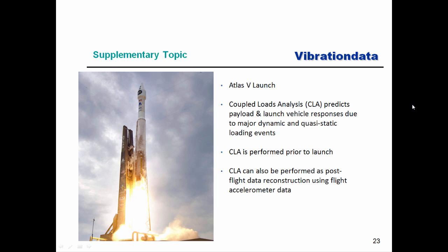And there's a finite element model for the launch vehicle, and it gets connected with a finite element model of the payload. Now, in some cases, that payload might be represented by what's called a Craig-Bampton model. And maybe in an upcoming webinar, we'll cover coupled loads analyses and Craig-Bampton models in earnest. But for right now, let's just consider that we're doing an overview. So the coupled loads analysis predicts the payload and launch vehicle combined response, or system level response, due to major dynamic and quasi-static loading events.